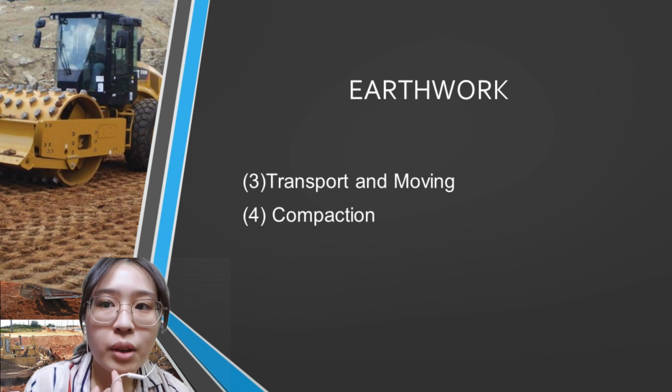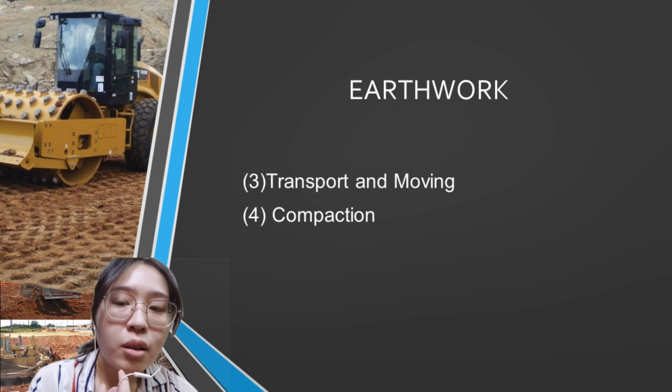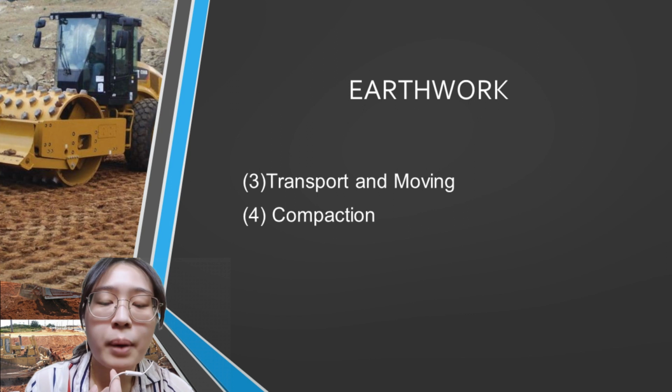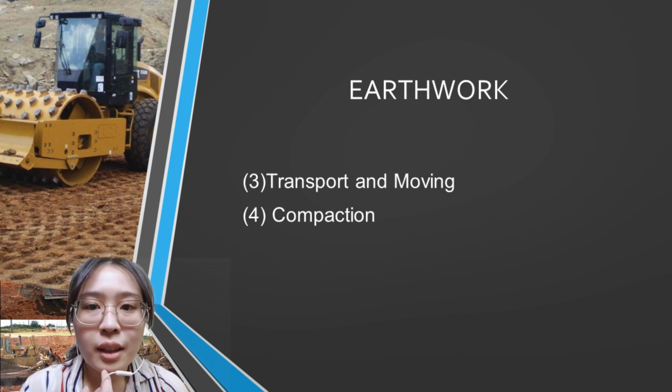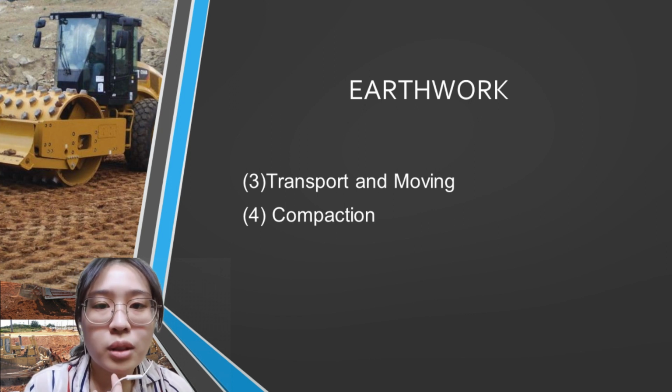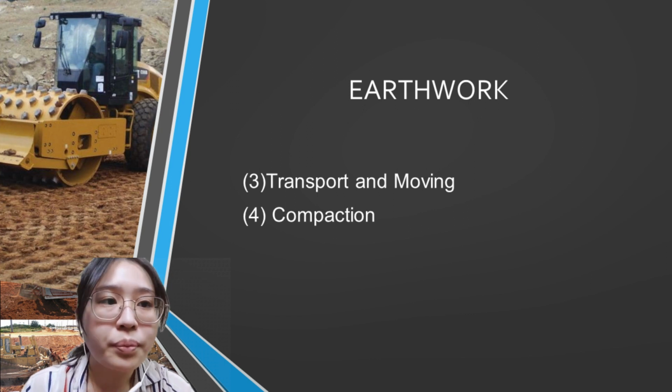So the third step of the earthwork is transport and moving. Here, all the excavated material will be transported by trucks. The last step is compaction, which is to reduce the soil permeability and also increase the bearing capacity of the soil.